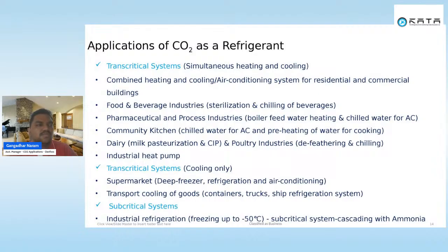In such a way, whatever fuel you are using in the boiler, such as LPG, CNG, coal, high-speed diesel, or light diesel oil, LDO, all these are very expensive fuels these days. So we can make some operating savings by giving 90 or 100 degrees hot water to the boiler instead of sending 30 degrees. And similarly, chilled water for the air conditioning application.